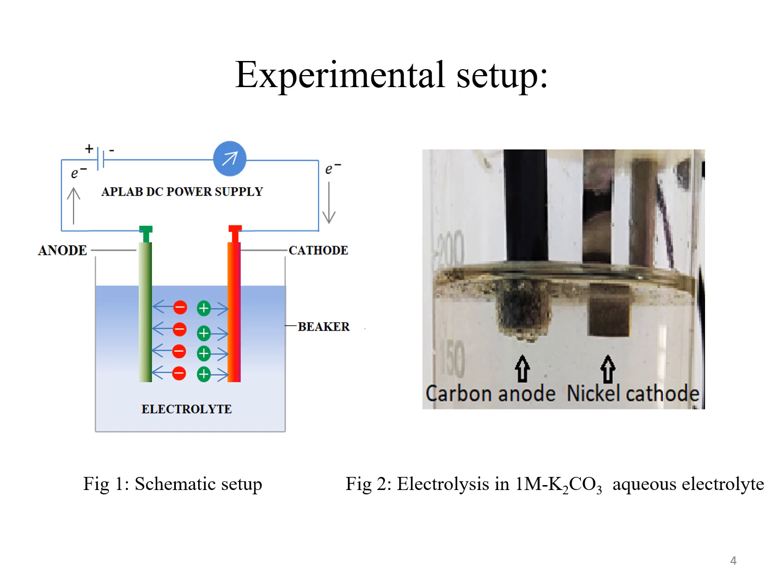The bias on the electrodes is in the range of 20 to 30 volts imposed via a 2 electrode setup. The power supply provides 1 to 4 ampere current in the circuit and the experiment is run throughout the pre-decided time range. A dry silicon carbide cutoff wheel is used to separate the dipped electrolyzed part of the cathode from the cathode part, which is suspended in the air.